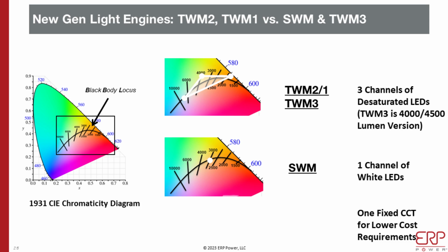By the way, since you asked that question, we do calibrate each one of these modules during manufacturing, because as you know, each LED is slightly different. That's why on the CIE chart each LED is not going to be exactly the same. We get thousands of LEDs that are pretty much the same bin, but even within the same bin they're within about 4 steps each, and we have 3 of these, so they're never going to be exactly the same. To assure that all of these are exactly on the BBL, we go through a calibration phase during manufacturing. That is how we guarantee it.